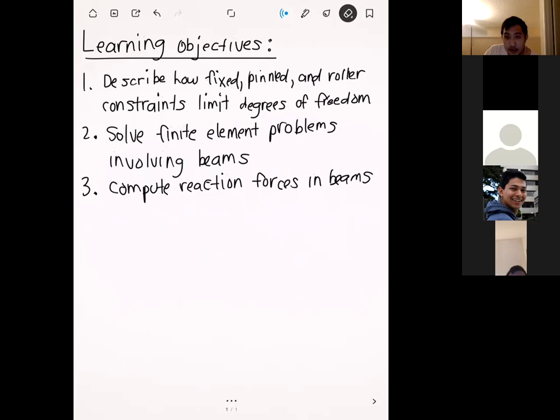Yeah, Houston. So to answer your question, we're basically assuming all isotropic materials right now, and so that's why we're able to use just a single value for the Young's modulus, and we'll see today too. We're going to use a single value. We're going to bring the moment of inertia into the equation too. So for anisotropic materials, you're going to have different strengths in different directions, and you can do that in ANSYS too. I do have a handout prepared for that, but I think we'll talk about it later in the semester when it becomes more relevant.